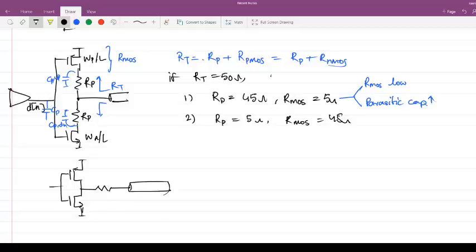In this case you see that the two nodes have now become one node. So here, if I count from the output, you have high to low and low to high, here you have made it one node. So this particular design often has lesser data dependent jitter as compared to the previous one.